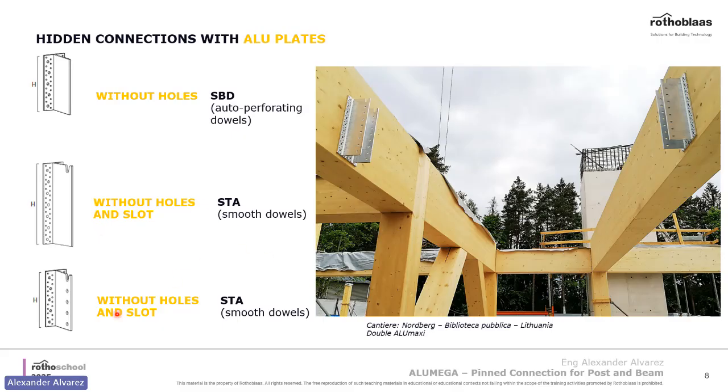Or sometimes you don't want that. You just want it to come into place, and drill the holes on the wood side only. Don't worry, we have that as well. We have knife plates with holes in them as well. Or you can just use self-drilling dowels and drill the dowels into the wood, and they will go into the knife plate. So that's one way to go about it.